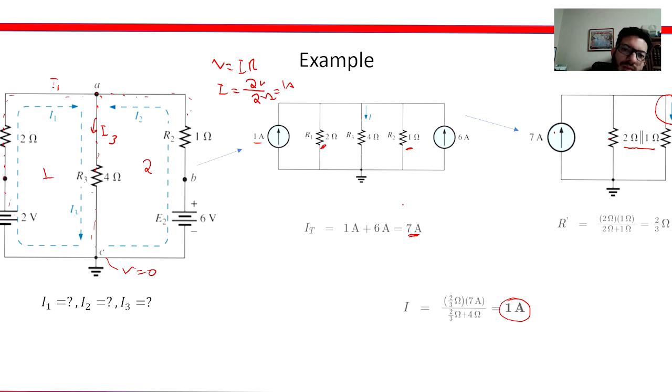Okay, and in that case, it's simpler to go ahead and find I1 and I2, but this is just showing the point of starting to use different methods to analyze the circuits. From here, it was simpler to go this way because we can do the equivalent resistance of the circuit, and then we can do the current divider rule here. In other words, we cannot find the equivalent resistance of everything because this current here is not the same as the current from here and here.